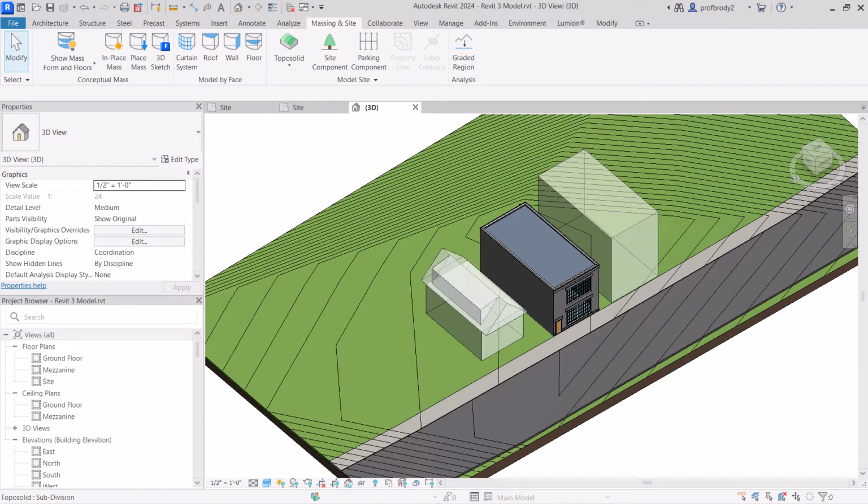So retaining walls, in theory, you could do this using the graded regions or split lines, but I think I'm just going to draw them as railings. And you might say, railings? What are you talking about? Well, I learned this from the Balkan architect, who is a genius at Revit. If you ever need to learn anything, he is the one to go to. And it's a great idea, super simple to do.